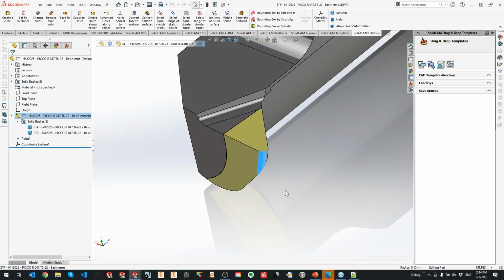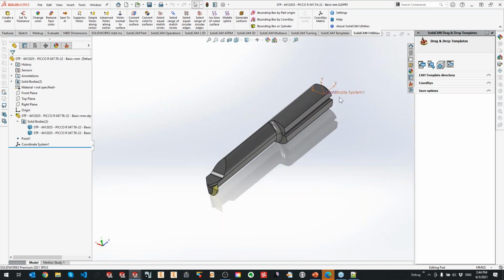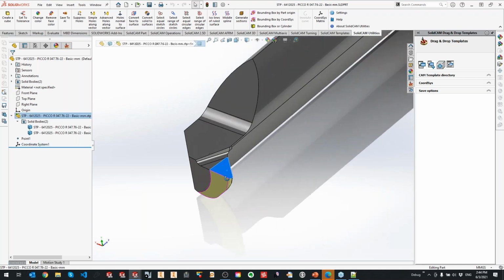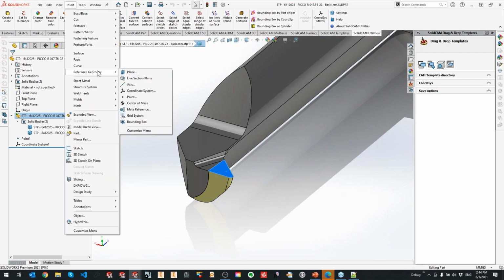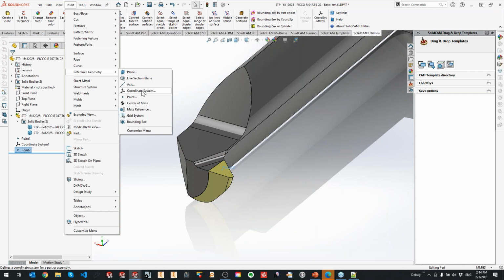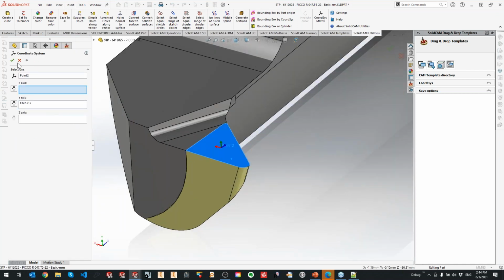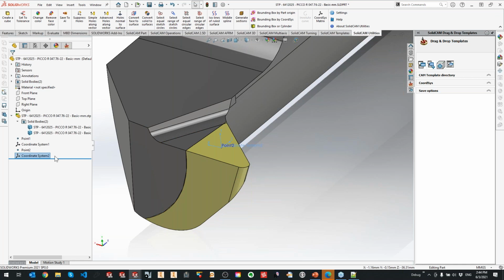As you can see, everything here is prepared. I didn't touch anything on this example, I just downloaded it, and in this case, I just defined this coordinate system to save time. But basically, I will just create a point over here and repeat the same process as I was doing before. My first coordinate system would be Y up, and I will call it insert joint coordinate system.